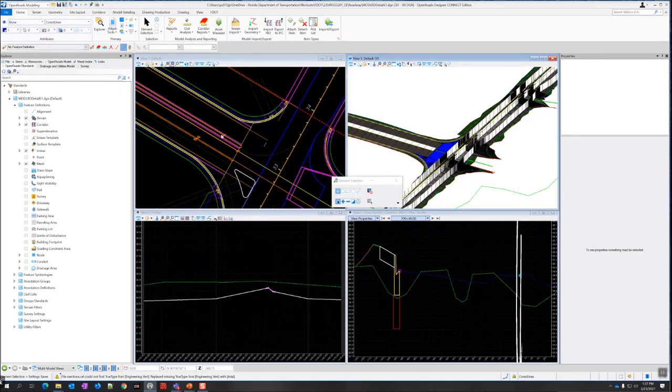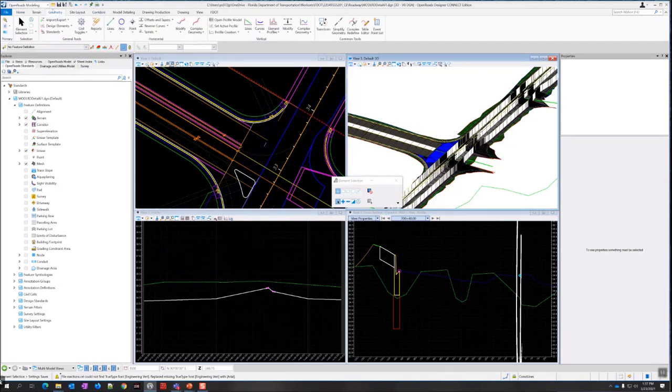All right, so I'm going to just use the same tools like we did before. Go to geometry, use these horizontal tools. First, I'm going to build a line. So let's call this one pavement crown for feature definition. So I'm going to set that first here. Linear roadway design, plan profile, 2D lines, pavement crown. Check this or select this button to use as active feature definition.